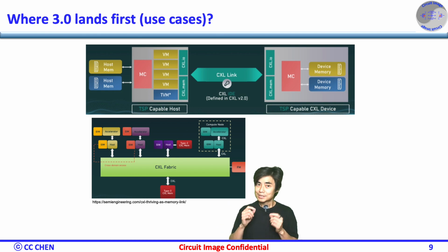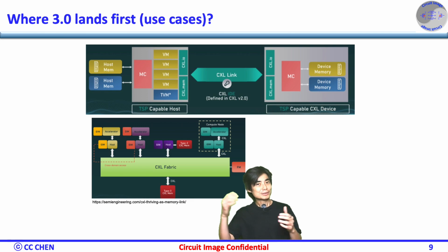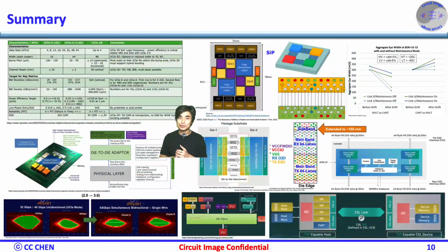Let's end with a simple rule you can apply today. Here is a summary showing why UCIe 3.0 is needed. UCIe 3.0 brings faster lanes and field-ready operations. If you are pin limited, use 64 gigatransfers per second to raise bandwidth density.